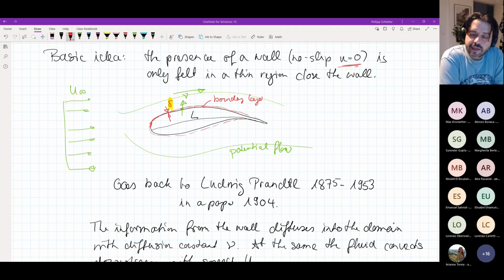The reason why I'm asking this is that it's quite an important knowledge to have when it comes to laminar boundary layers, because it's always the same type of growth. And it very quickly allows you to assess how thick such a boundary layer actually becomes, and also what happens if you make the body, let's say, twice as long, whether it doubles or not. Okay, I see now the answers. And most of you say it grows as a square root with distance. So that means if I make the body 4 times longer, it only grows by a factor of 2, let's say.